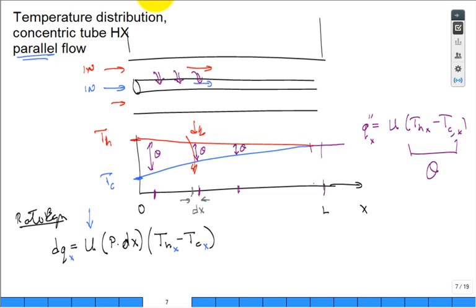Now, coming out of Thermo 1, energy is conserved. So out of Thermo 1, you have energy balance concepts. You've mastered those energy balance concepts. They still apply in heat transfer. So this little dq that comes out of the hot fluid results in a rate of change of the hot fluid temperature as I'm moving down the tube. Let me try and describe that. That's like the slope of this line. Well, with respect to x, it's decreasing. The hot fluid temperature is going down as I increase x, as I march further and further down the tube.